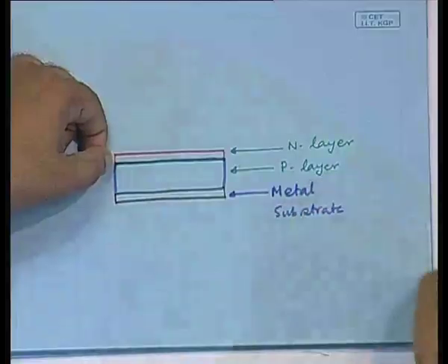So, metal fingers are put and then that is removed, let dry, and finally, you have the whole thing ready. All these individual cells are connected in series in order to produce a whole panel. Each individual cell will be producing a voltage of the order of 0.8 volts, which is not sufficient for any practical purpose. So, many of them are put in series to produce a voltage of say 30 volts, which is a useful voltage, and that is how the solar panels are made.